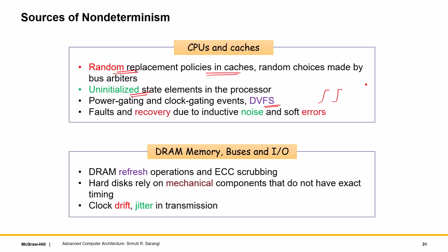It is possible that a hardware interrupt arrives at the time of a DVFS recovery and it is missed, and that causes some problem, right? But next time when I run it, it may happen that I recovered from DVFS much faster. My PLL was able to lock far sooner. So I don't get to see it.